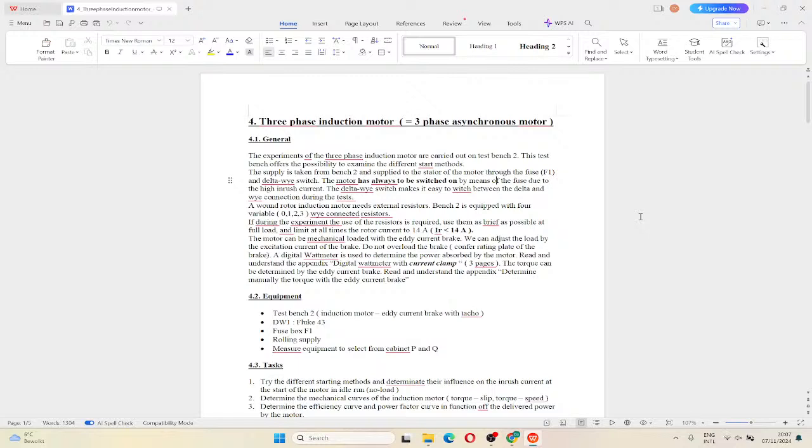So do you have a question about this circuit diagram? For the start test, we do not need any load. So we just do 4 different tests, like what is shown in this table. We use 2 delta and 2 y with different resistance. And what we need to measure is... so the delta configuration is on the stator side, right? Yes, on the stator side.